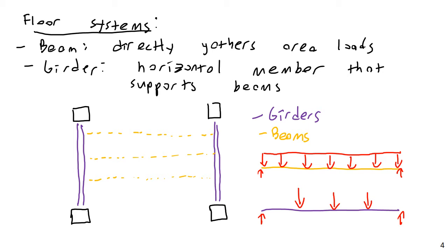So if I did a vaulted ceiling, is it still a beam? The question is, is it still carrying the load? It would be a combination of beam and column at that point. There would be bending in there, but also substantial axial force. So the members in a vaulted ceiling we refer to as beam columns, because they have both axial force and moment present in them.